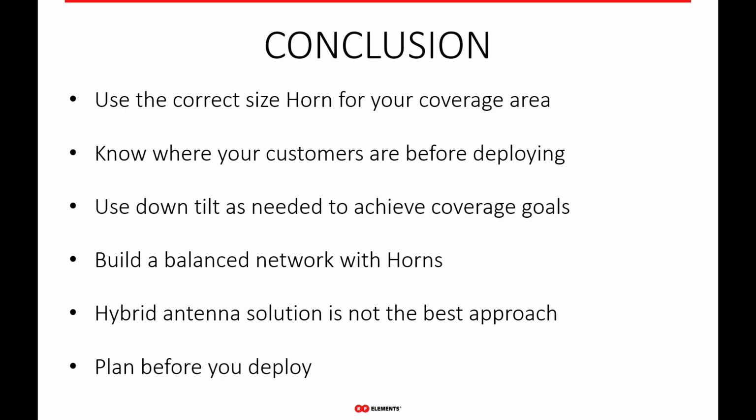And again, the biggest thing is plan before you deploy. If you look at pretty much everything I've said here in the conclusion, it's all about planning before you do anything with our horns. So know where your customers are, plan what kind of coverage area you want, how far you want to go, find out what kind of downtilt you're going to need to achieve these goals, build or plan based on a balanced network, and decide whether you're going to stay at a hybrid solution forever, or migrate to horns later.